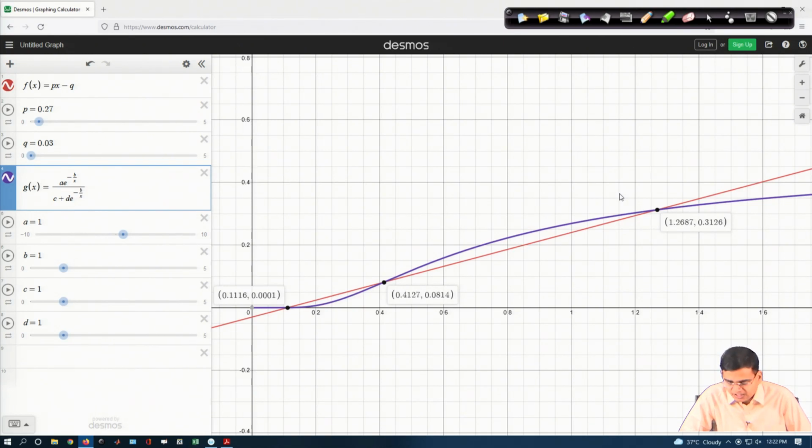Now, the question is, how can you have 3 steady state temperatures for the same state of your system, same flow rate, same feed temperature, same jacket temperature and so on? Well, because the system is non-linear. Okay. So, since the system is non-linear, now you have the intersection of your heat generation curve, which is a non-linear curve, with your heat removal curve, which is a straight line, right.